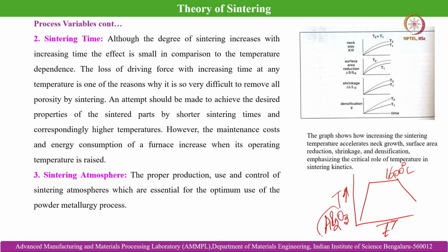Here is an interesting concept to understand. As we increase the sintering time, up to a certain extent we see an increase in sintered density, but beyond a particular time, if we increase the sintering time further, then we will experience grain coarsening as well as pore coarsening, because there is not much change in the density of the sintered part beyond a trade-off time.